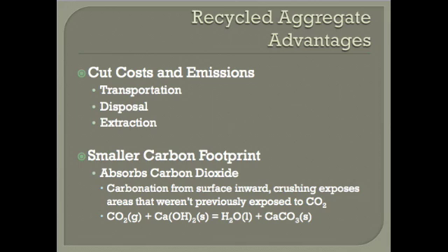A less well-known benefit of recycling concrete is that recycled aggregates absorb carbon dioxide and thus have a smaller carbon footprint. Calcium carbonate is the material that gives concrete its strength. A simplified chemical reaction shows that the carbon dioxide reacts to yield calcium carbonate. This process happens from the outside in, and when concrete is crushed to be reused, areas that weren't previously exposed are and can react with carbon dioxide.